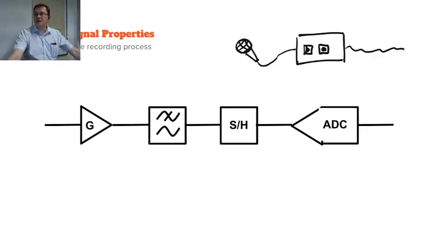Some of the A to D converters are less sensitive to the out-of-band noise, but at some point you need that low pass filtering done.